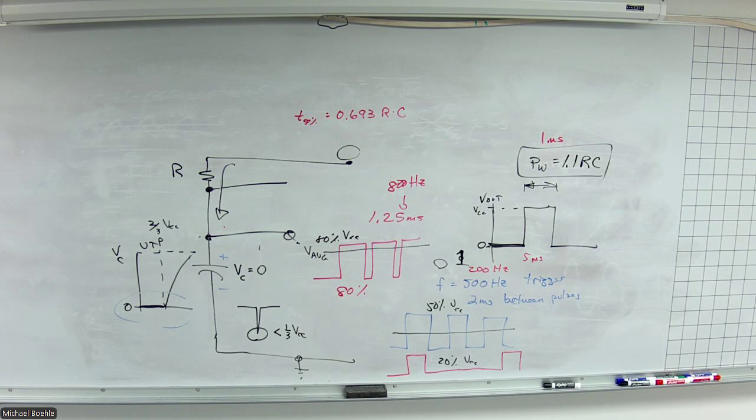This would be a noisy RF line. Oh, RF, I wouldn't do this for RF. With the 555 timer, because you're using R's and C's, you're limited. In the past, sometimes, if I had more time or thought about it ahead of time, I've built oscillators using the relaxation oscillator that we covered in chapter 20, and I've done oscillators using a 555 timer. You find that, especially with the 741, the slew rate really limits the upper frequency that looks nice as a relaxation oscillator.